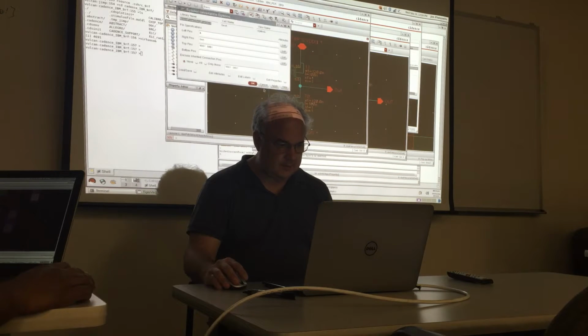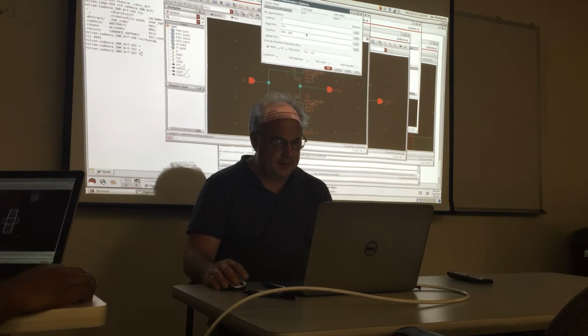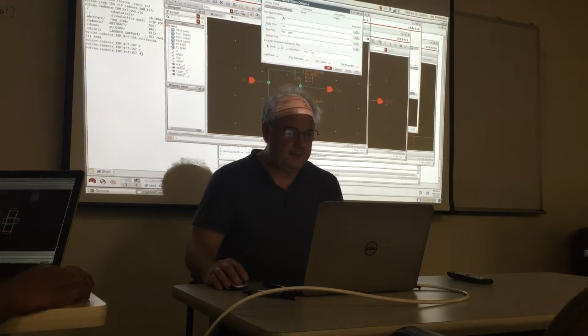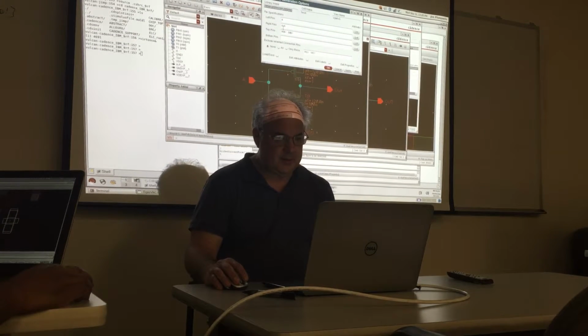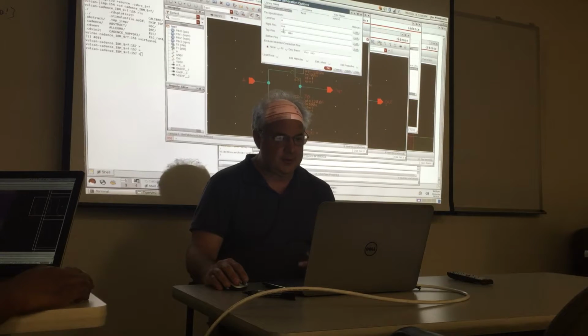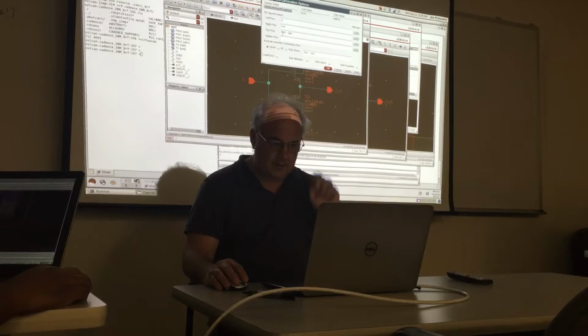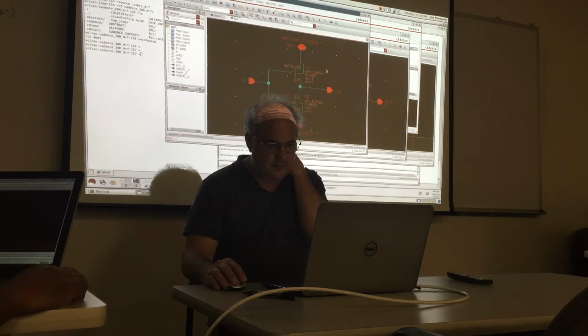I'm gonna replace it. Right, and then before you hit the go button here, pay attention to where these are, because it saves some work. The defaults are usually good, but sometimes it gets it wrong. If you've done your inputs and outputs correctly, you'll want to put the inputs on the left, the outputs on the right, and then of course the pins, it'll make them both at the top. VDD bang, ground bang. I think that's good for this guy.